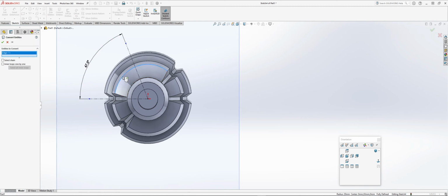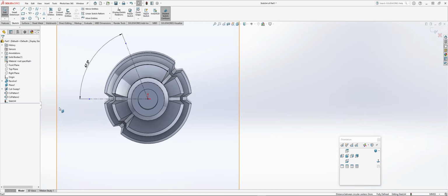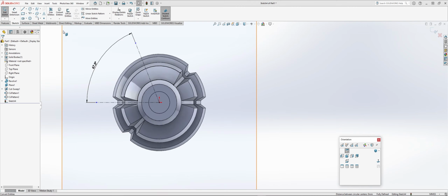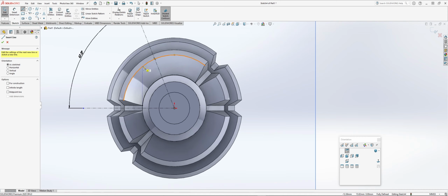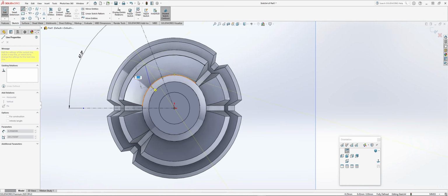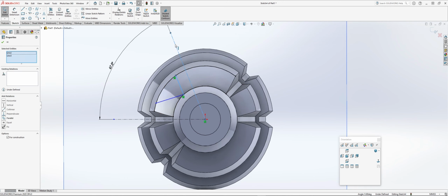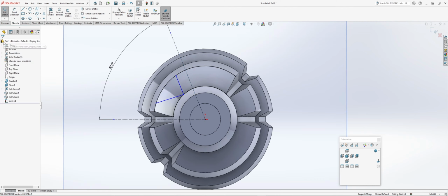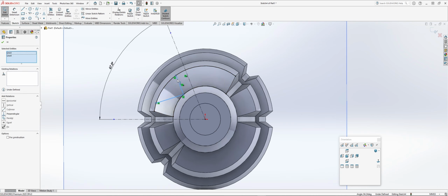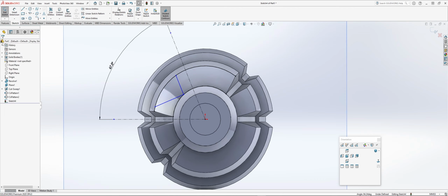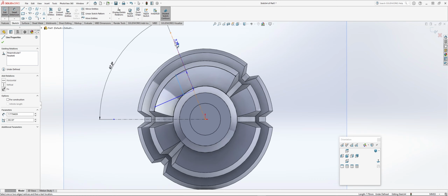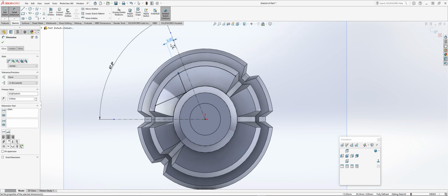We will convert this outer circle and the inner circle when we need this. Okay. Choose a line from the circle. Don't choose any of the suggestions. Put it there, and then somewhere on the edge again. Okay, so let's look at the relationships. I can select the two lines by holding down the shift key. We know that these two lines are parallel. Then we check this line and this line, and we know that they are perpendicular. Okay. Distance was 3 millimeters.